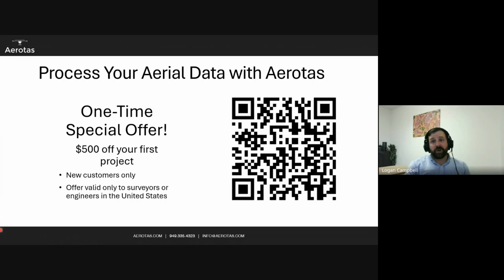For non-DJI drones, we typically start with the LAS file. It has to at least be an LAS file, even if it's not georeferenced, because those steps are often controlled by the proprietary vendor and extraordinarily complex for that individual vendor, and there's just not enough volume for us to be able to buy each individual software and become proficient in those really, really complex ones. That's why I go back to that first step is typically controlled by the vendor. So the more bespoke and complex the system, we probably start with an LAS file. Unless it's a DJI system, then we go from there.